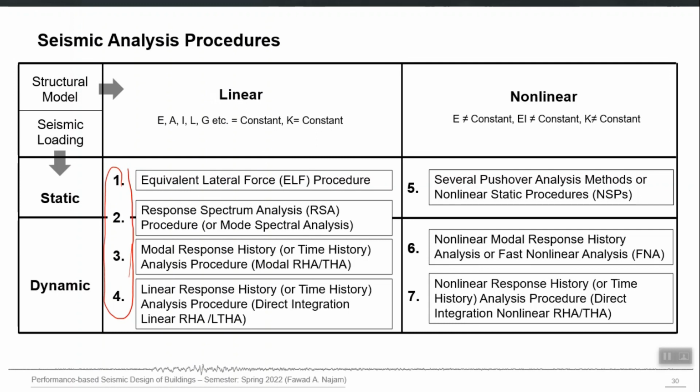It will deviate from linear, and that deviation we will be keeping in the allowable range or safe range, right. So if it can follow that deviated path without losing its load carrying capacity, then we are safe, right. So this is the seismic design philosophy in a nutshell if we are following the first 4 methods, right.